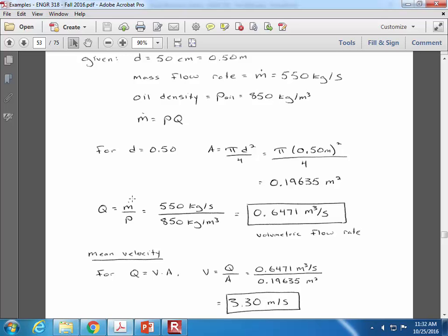Hydrologic engineering is kind of the study of watersheds, and in hydraulics next semester, we'll be designing pipe networks, and you always start with sort of a given flow rate. Q is given to you, the designer, and then you have to say how big the pipe should be based on that. Well, hydrology, which is this new class I'm talking about, gives you the flow rate Q. It looks at rainfall patterns, the size of watersheds, the type of land cover and the type of soil. And there are models for predicting what the runoff flow would be. So it's very relevant to the types of flooding that we had in West Virginia over the summer.